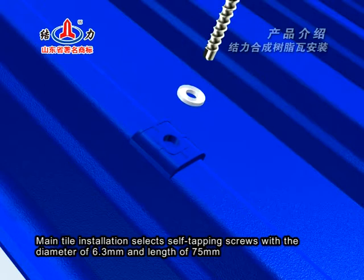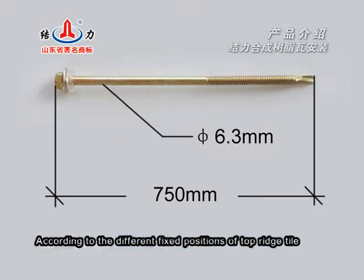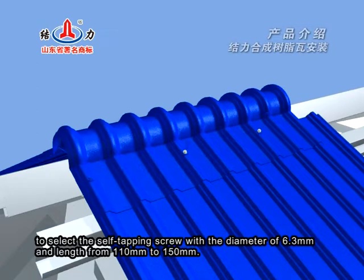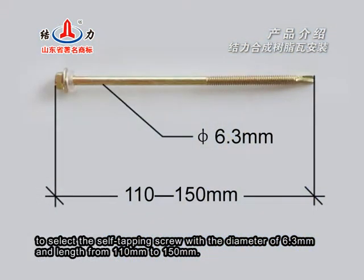Main tile installation selects self-tapping screws with the diameter of 6.3 mm and length of 75 mm. According to the different fixed positions of top ridge tile, select the self-tapping screw with the diameter of 6.3 mm and length from 110 mm to 150 mm.